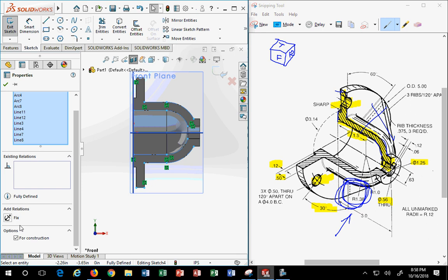The reason I say this, just telling you up front from experience, is that when you deal with a lot of odd-shaped objects, organic geometry, and you use convert entities, or in the case of odd-shaped geometry intersection curve, those lines that it generates can actually fight you when making the sketch that you want to make. By turning everything into construction, it allows you to use it, but it doesn't fight you to make your sketch.